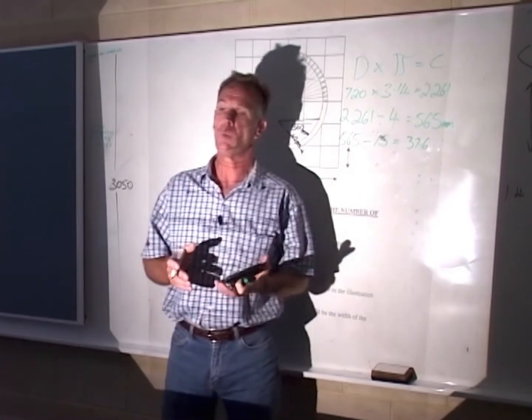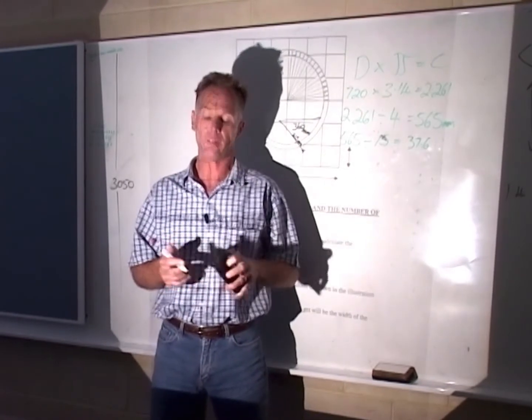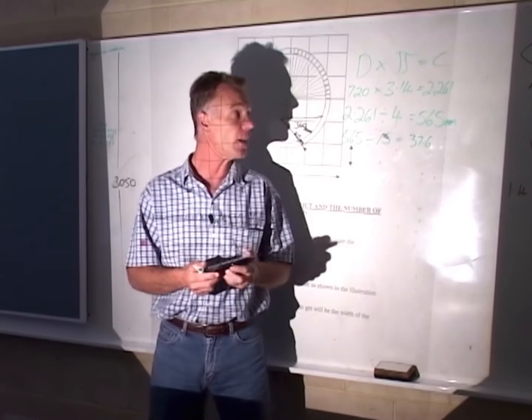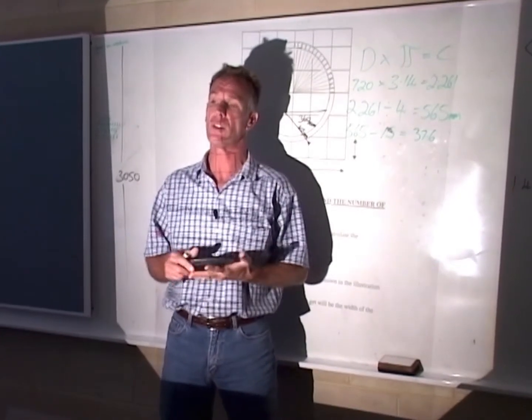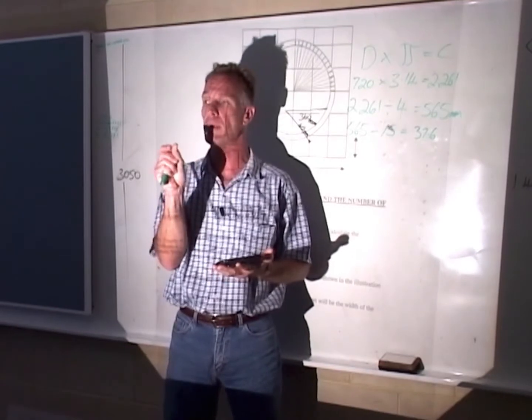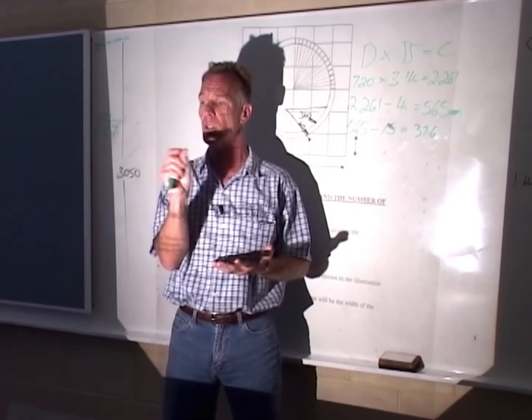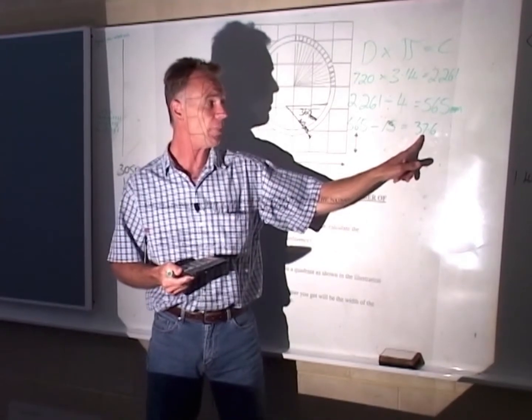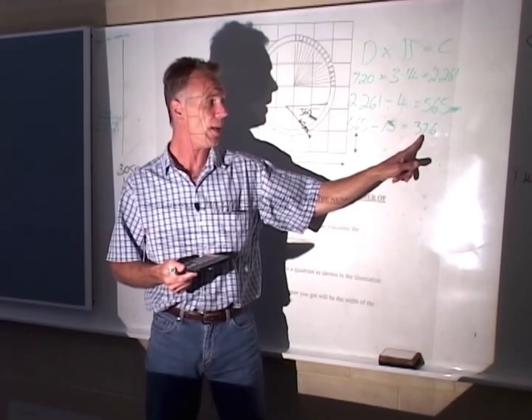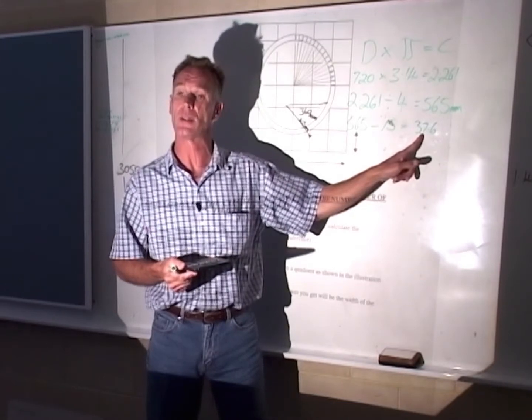Guys, don't forget, when you measure, when you formulate and when you do these calculations and formulate the size of each one of these individual tiles, you're going to require a 2 millimetre gap between each tile, which obviously will be grouted later. Now, that'll simply come off your measurement here, and you'll allow for that when you're doing your cuts.